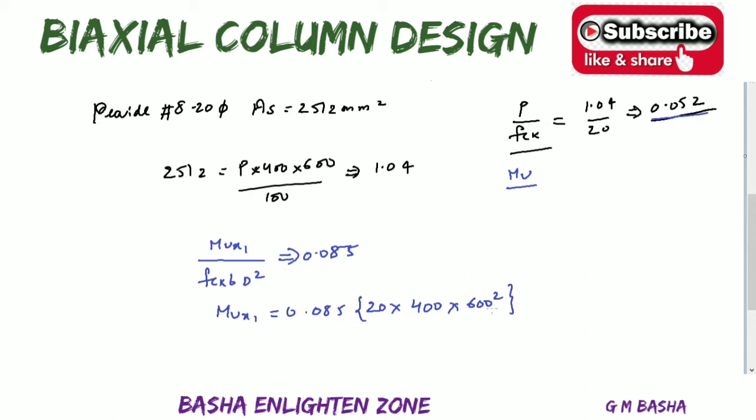And whatever values you have will be in terms of mm and Newton, so the values in terms of kilonewton meter, therefore you take 10 to the power of minus 6, to convert from mm to meters. If you simplify this, you will get around 245 kilonewton meter.